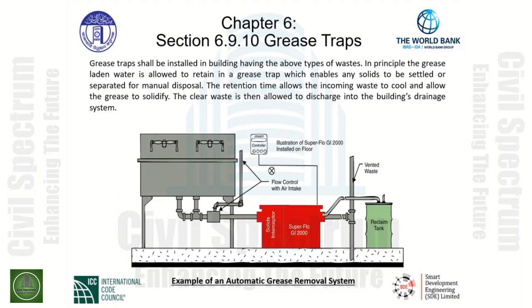Once the solidified grease is in this chamber, there is a timer and a heater that will heat up the grease in this particular chamber and allow a vacuum type system to draw off the now heated up liquefied grease into a reclamation tank. This will provide a storage for any grease that has been drawn off the system. Again, an automatic grease removal system.